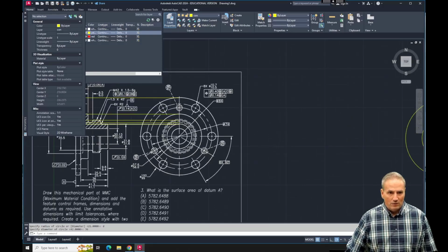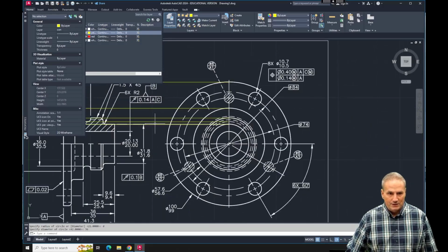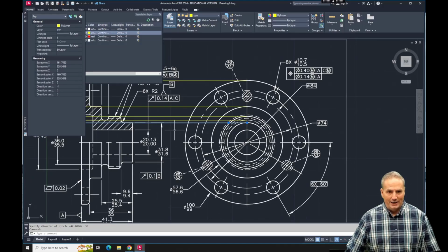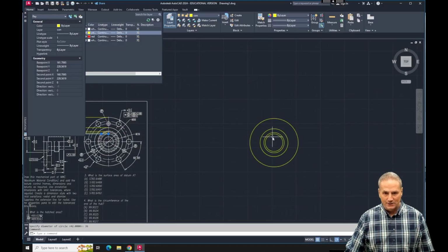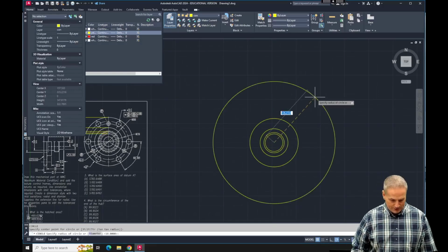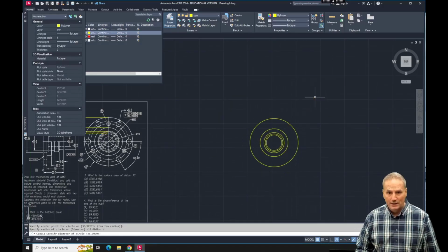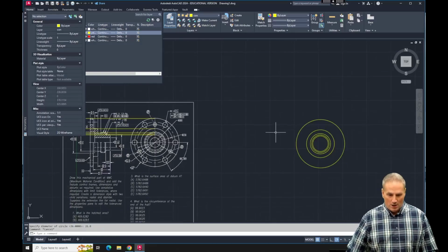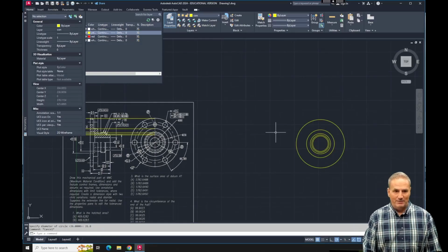And then the last one we wanted is going to be here. Again, that's going to be the bigger. So we want a diameter of 31.8. So we could say circle. One more time, diameter 31.8. Okay, cool. Now let's just do maybe an X line or something.